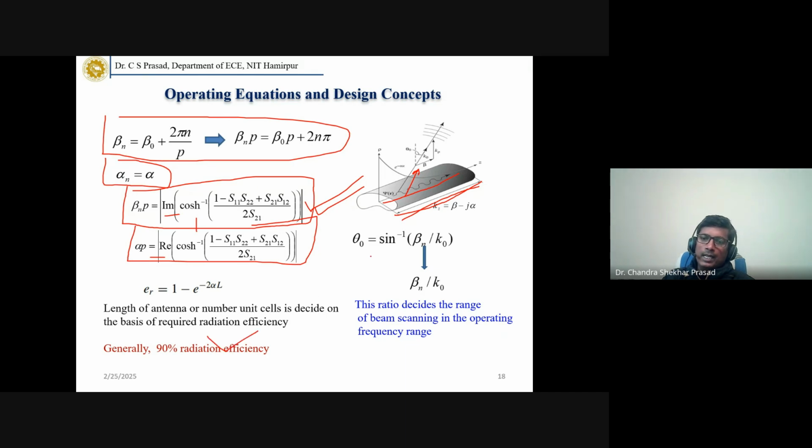The meaning of this is, let's say you put in 1 watt of power, and at the second port we get 0.1 watt. That means 0.9 watt, or 90% of the power, has been radiated or lost, because if you have some structure, there will be some loss also.